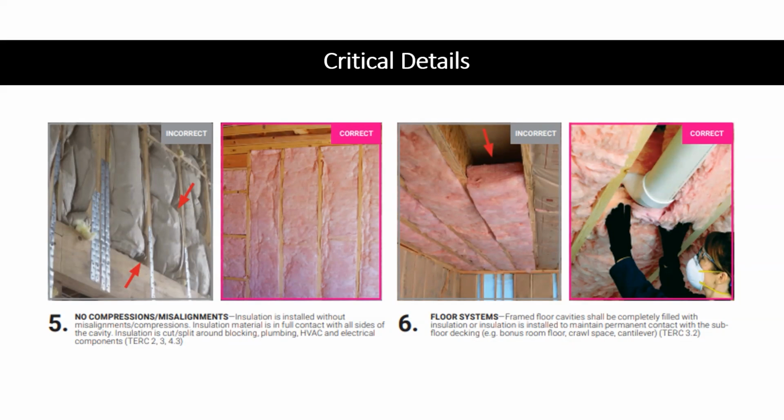But then you start looking at floors over anything: floors over garage, floor over crawl space, floor over unconditioned basements, floor over the outside. And you look at, is it properly placed in the right location? Is it in contact with the conditioned side? This is a quick, easy side snapshot of it's not. On the left, it's not in contact with the floor above. I'm assuming that this is a garage we're standing in. It may not be. But it's not in contact with the floor above.